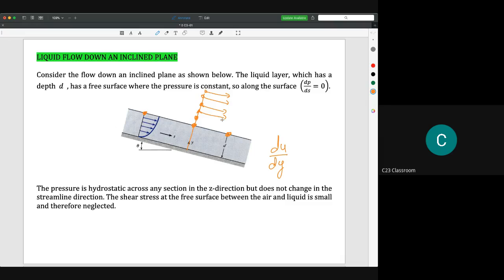So in reality, we could say that there is no liquid beyond this point, so there are no changes anymore. The velocity u at this point will become constant at any y, at any d. That's why we could say that the gradient du/dy does not exist anymore, so it is equal to 0 at y equal to d. Okay, can you understand that meaning? Yes, Ken, thank you. Okay.